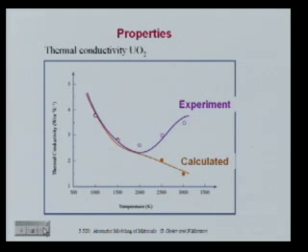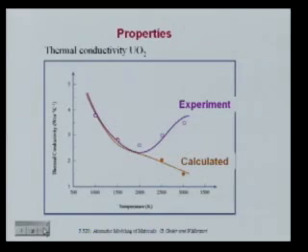Yes, sir. So then is configurational entropy driving the energy down? Or how is this interfacial energy defined? It's not just configurational entropy that's driving it down. Well, how is it defined? It's defined by looking at the energy of the two pieces together, and then the energy of the two in the bulk with the same driving chemical potentials.